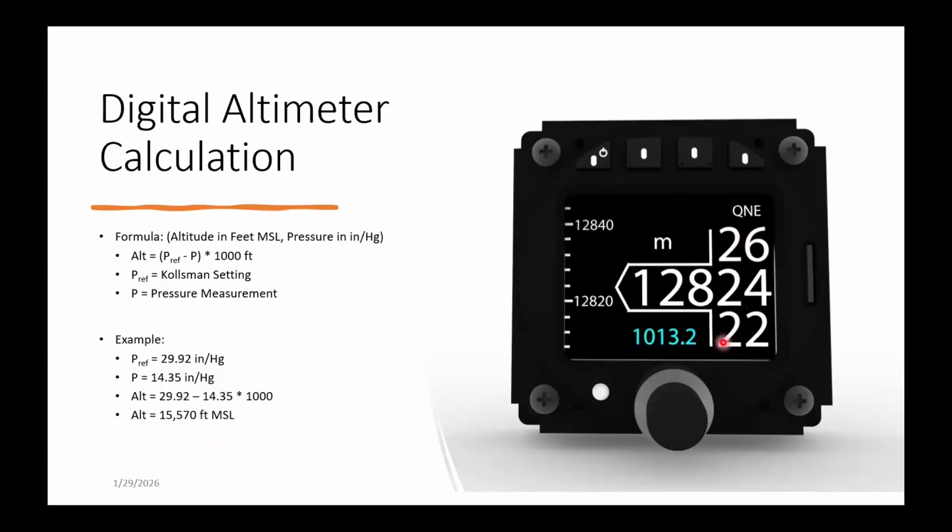No, I didn't try it. This is the Air Avionics ACD 57. I'm just using it as an example. One of its displays is an altimeter. By the way, it is a TSO certified altimeter, so you could put it in an aircraft with standard airworthiness if you needed to. And so in this one, your Kollsman setting is right here, and the units for your altitude, this one's reading in meters, and the value is 1,284 meters. You've got a little scale over here to help you set that so it's not just an abstract number, to help you bracket it.